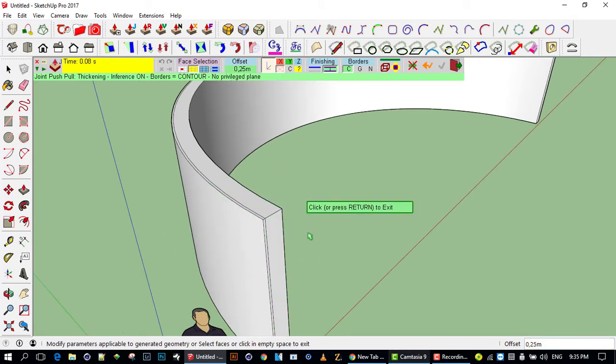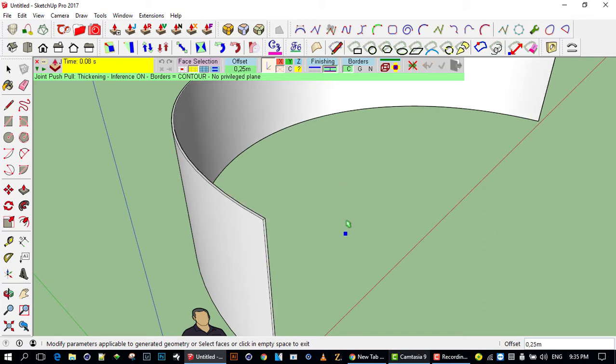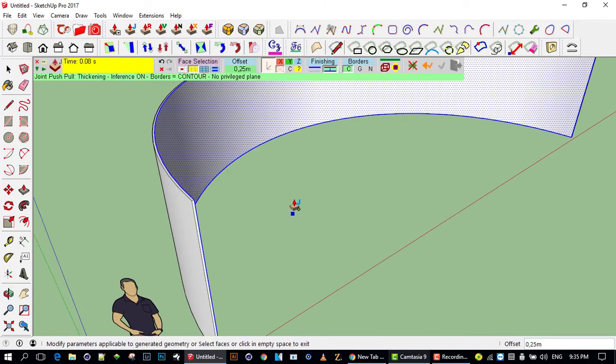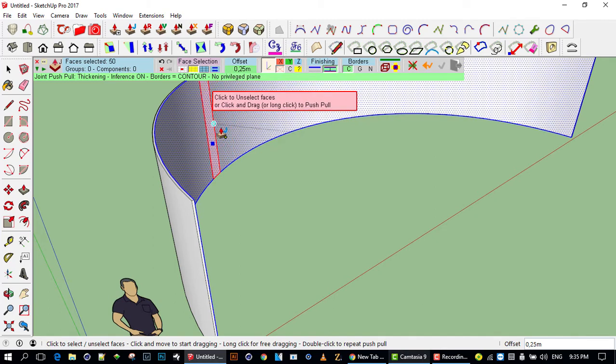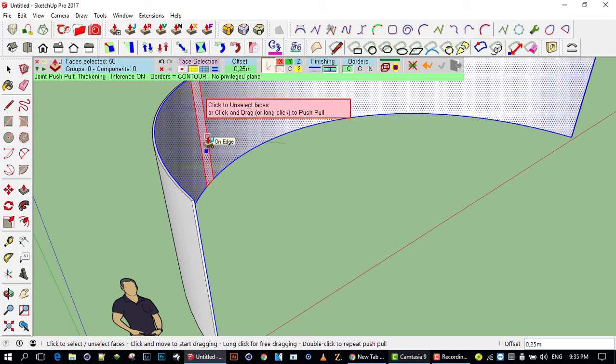Okay, the only difference here is that now I'm sitting with an extra extrusion, so there's 2 areas. So why did that happen? I'm going to go Control Z. Let me show you. When I click onto the surface that I want to extrude, if I hover over the area, you can see the push-pull tool shows the little push-pull icon, but there's a plus sign.